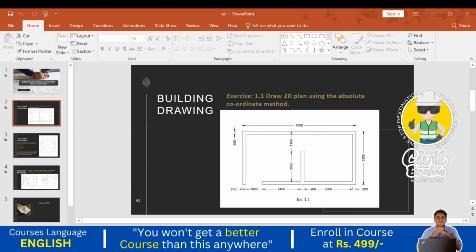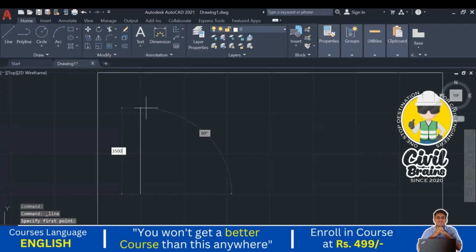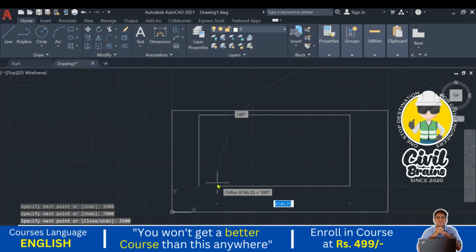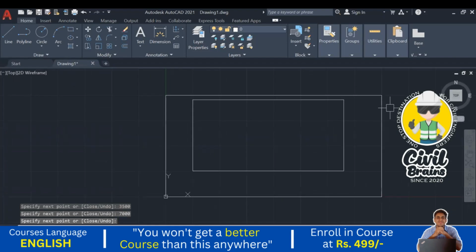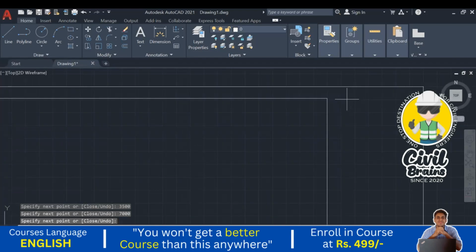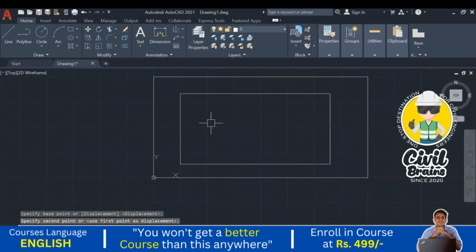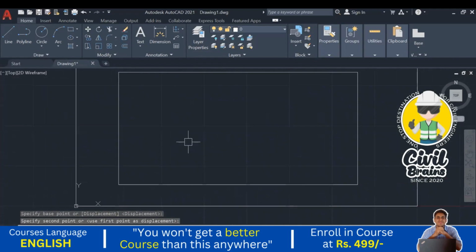Okay, I just go to the line command. I take the lower left corner as the first point. What is the height? 3500, correct? What is the width? 7000. Okay, depth 3500 and 7000. Press enter. Then I take this and make it in the center using the move command. So this is our outer walls.